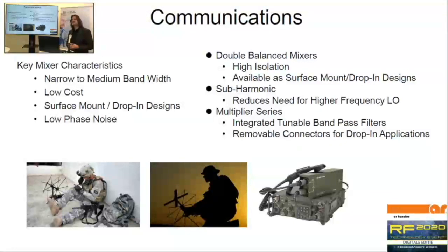Which mixers do we need? Well, we can use double balanced mixers, which give a high isolation. They are available in surface mount designs and drop-in designs as well. You can design one yourself depending on where you are. And then depending on the frequency you want to use, subharmonic mixing might be of interest as well.